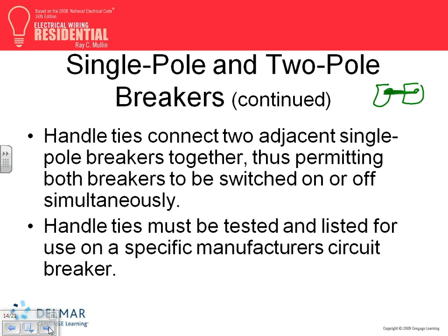They used to tie them, guys, by taking a tiny little copper wire, stripping the insulation, and bending the copper wire around both sides. Now these are tied together, and they use them on a multi-wire branch circuit or a two-pole. That's not an approved method. The approved method in the factory is to have them coupled with an approved method.